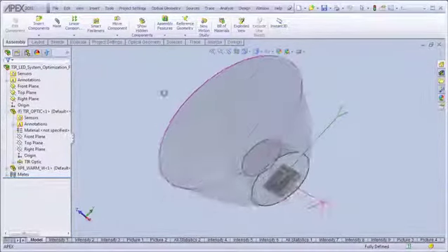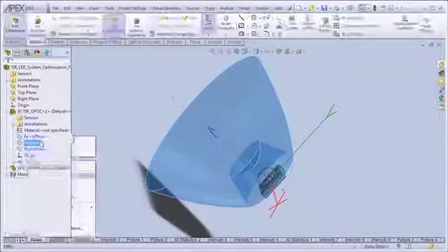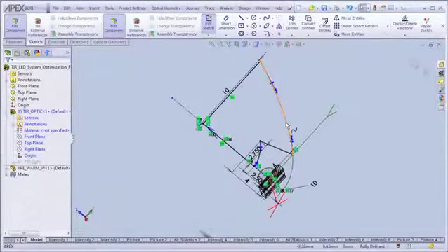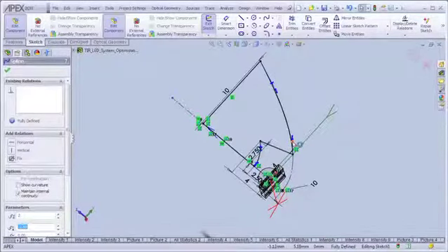Here's another example of a TIR reflector. The TIR reflector is composed of both reflecting and refracting surface elements. Apex's optimization allows you to control spline tangent radial directions and weightings, which in turn control the shape of curves, and changing these parameters allows you to change the curve shapes in order to meet your optimization goals.